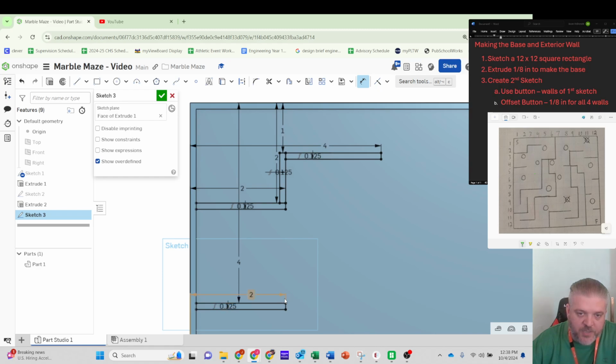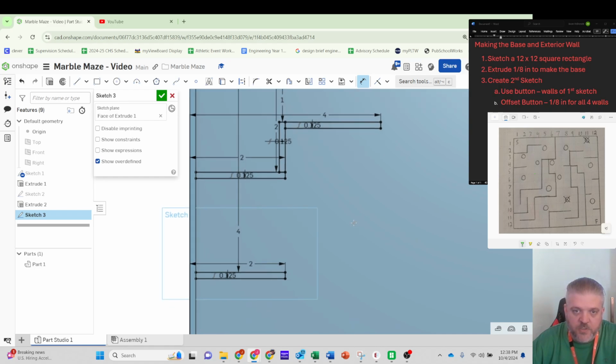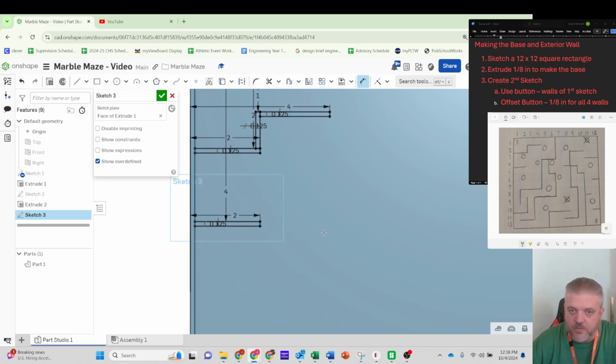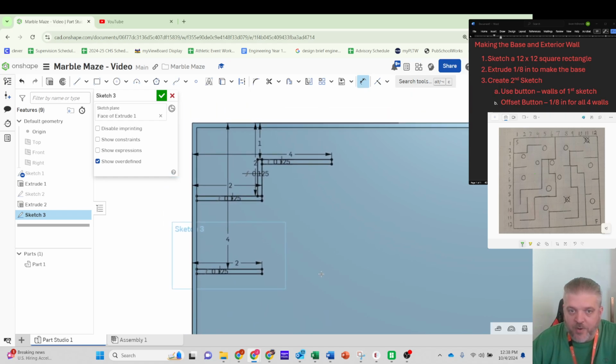So this would really be at 2 1/8 inch if I had dimensioned it to be 2 inches wide. So it's hypercritical to know which line is your zero, where you're putting walls, so that you get the right dimensions. At this point, I'm going to pause the video, and we'll be back in just a second to show you what the rest of this looks like once I've drawn in all of the dimensions and all of the walls.